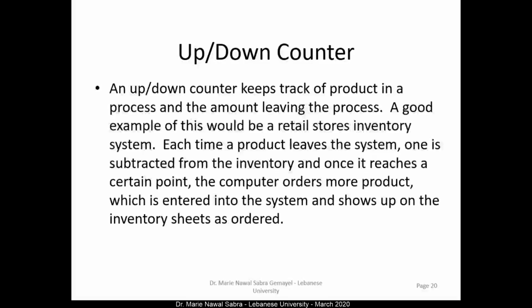The up-down counter is very practical whenever you have a vat or a batch and you have a quantity of material coming inside and a quantity of material coming outside, and you really want to know how much is left within the batch. So instead of using 2 counters and subtracting, you can just use an up-down counter with 2 different inputs.